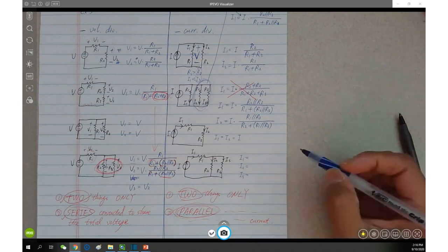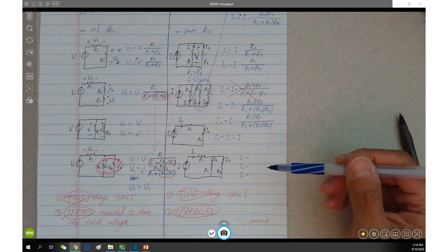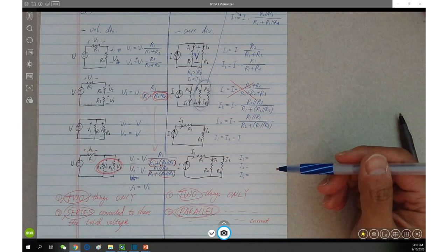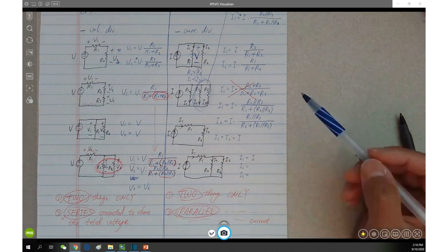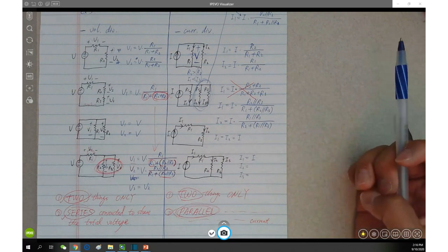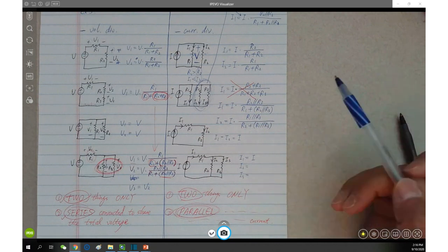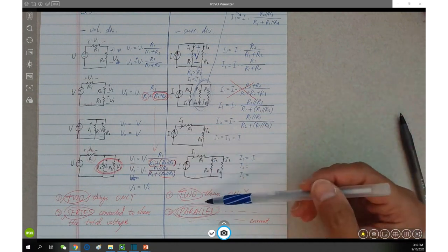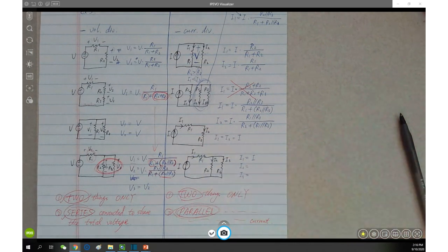All right, let's take a look at the solution here. So I1 equals what, first of all? Anyone? Yep, Shane is right. Be very careful. R1 is not dividing the current. It's not part of the current divider. R1 is in series with the current source, so the current through R1 is nothing but the current source current. It's series connected. It's not a current divider.